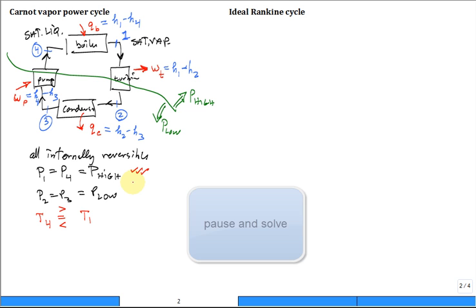I'm sorry I can't go and visit everybody, but this is one of those mind-warping questions you get in Thermo 1. So you're dumping a whole lot of heat into the working fluid. It's a boiler. You're putting heat in, heat in, heat in. We already said it was constant pressure. There are no irreversibilities, no friction. There's no pump to boost the pressure, no device to take it away. We neglect pressure loss. It's the same pressure in, the same pressure out. True? It comes in saturated liquid, goes out saturated vapor. So what's the temperature? It has to be the same.